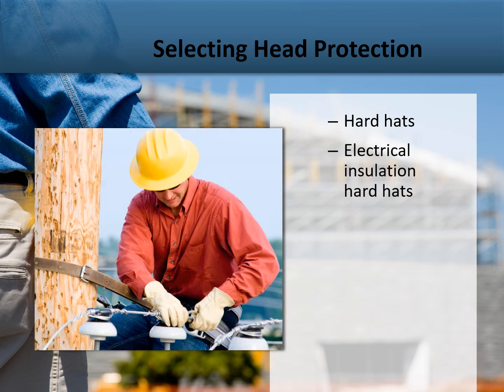Electrical insulation hard hats are used to reduce the risk of electrical shock and can protect against such hazards as power lines. However, do not assume that a hard hat will protect against electrical hazards just because it is not made of metal.